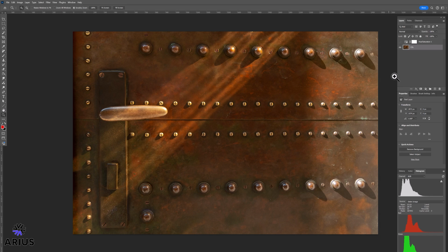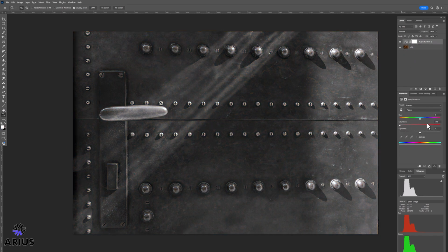Open the original color image in Photoshop and apply an adjustment layer to create a grayscale version. And consider the tones and what they will give you in elevation. All these tones become shades of gray and will affect the underlying surface to a greater or lesser degree, based on how dark each is.